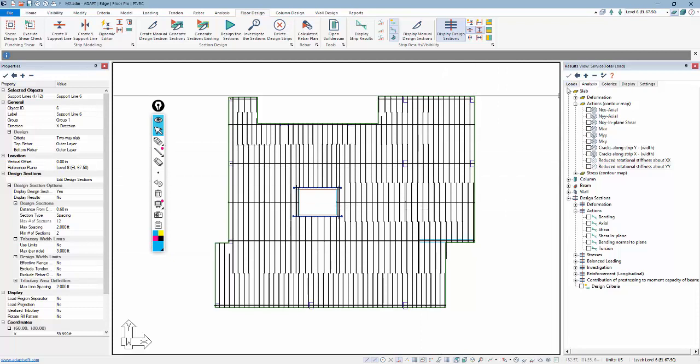And that's all judged and designed, we'll call it, through requirements that are given in whatever design code you're working in. Some design codes are a little more lenient with the ability to exceed an allowable stress, but then add reinforcement for crack control. And then there are other codes where you have to meet hard limits for allowable stress.